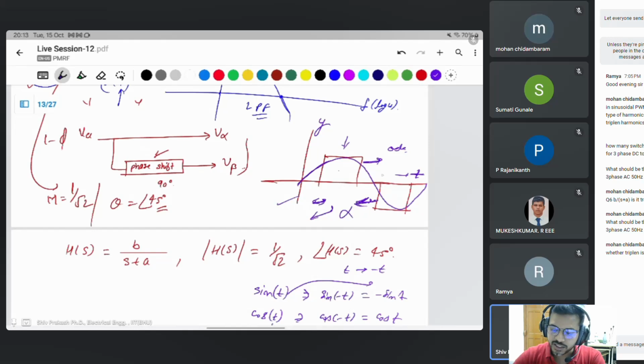because the voltage signal is like that only in pulses, DC pulses, not a sinusoidal, not any other signal. It is simply pulses, square wave, known as DC pulses. Then for finding the harmonics, you have to use the Fourier analysis. Then you will get the harmonics.